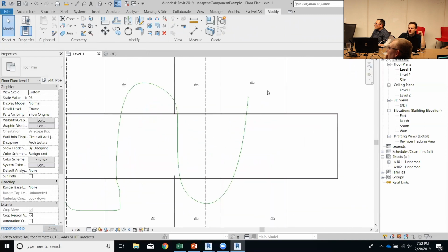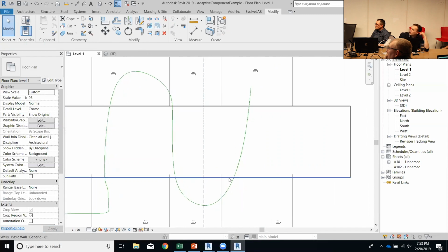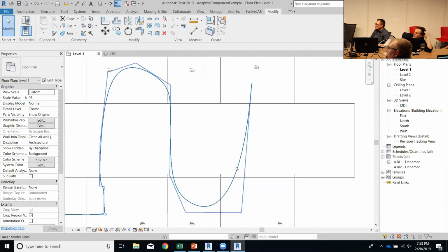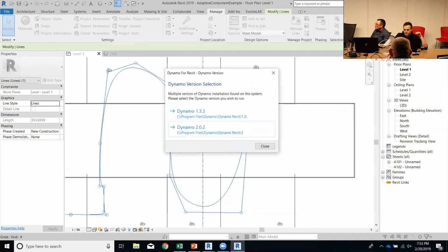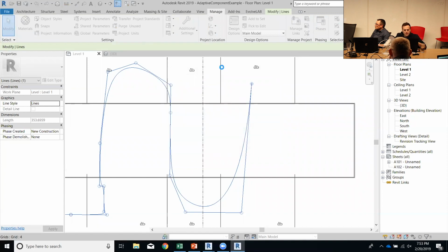For practical reasons, I wanted to be able to renumber. This is room number 200, 201, 202, 203, 204, etc. Well, typically when you're modeling this, you're just placing these rooms fairly irrationally. However, you can have someone who might know that room numbering logic and have them build a model curve. So then what we're able to do is take that model curve. I can't remember if this was a 2.0 or 1.3 script, so I could be regretting my own decision here in a second.